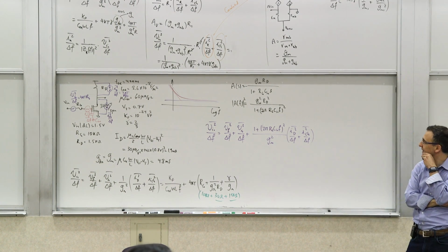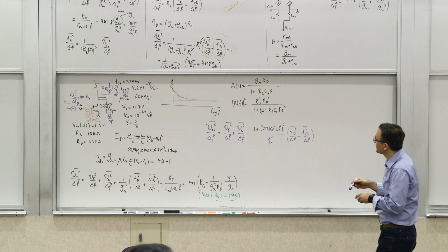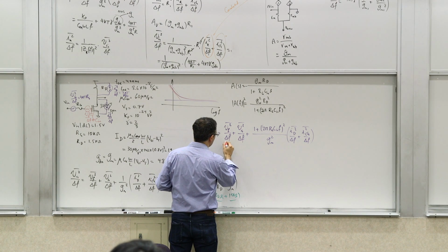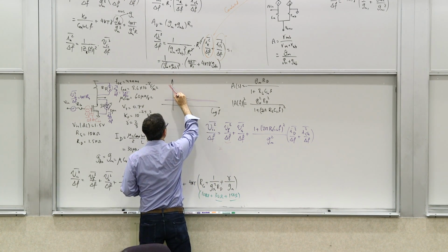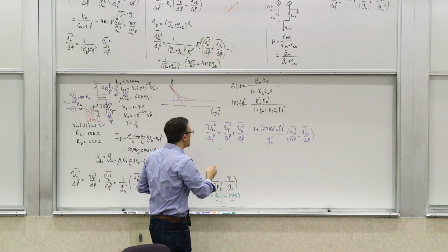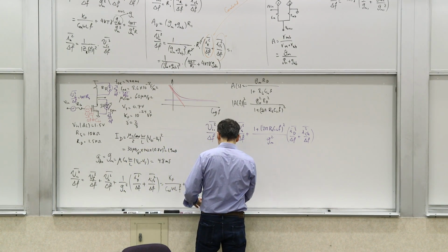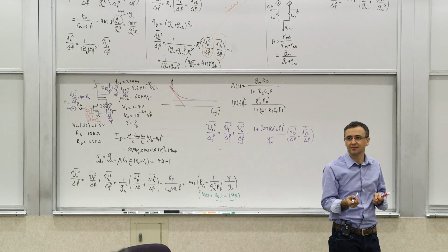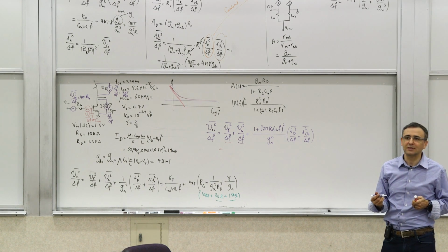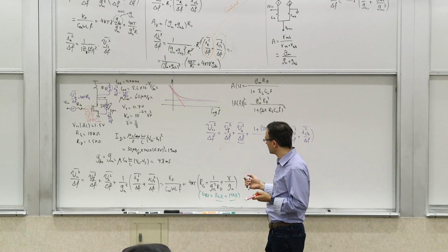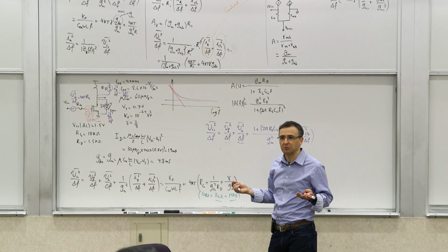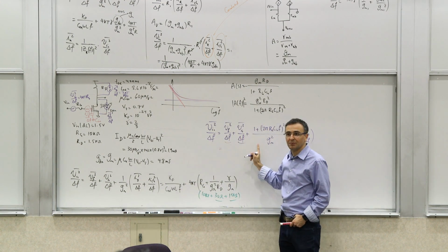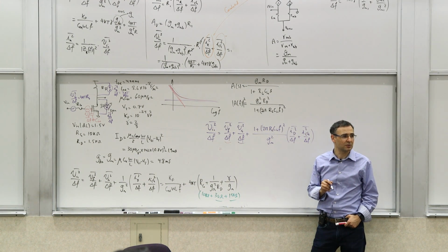What does that mean? How does this look? I mean, you can explicitly write these things, right? So this part is the flicker noise. This is the 1 over F noise. So this is still there in the power spectrum. This part is the noise of the input resistance. Now, whatever value, that value obviously was clearly crazy, right? Too high. But if you even just change that from 10 kilo ohm to 100 ohms, it would still produce some value. But it doesn't matter. But that's white noise. That's not affected by this transfer function, because that was already at the input.